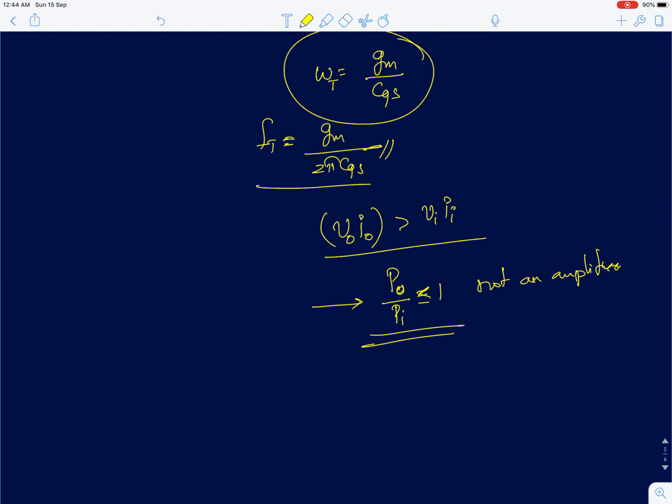So that's all I wanted to discuss today about the comparison between MOS versus BJT. Some important parameters: we said that the GM of a BJT is always greater than that of a MOSFET, and for both a MOSFET and a BJT, the intrinsic gain A0, the maximum gain, is independent of the bias current, IDQ for a MOSFET and ICQ for a BJT.